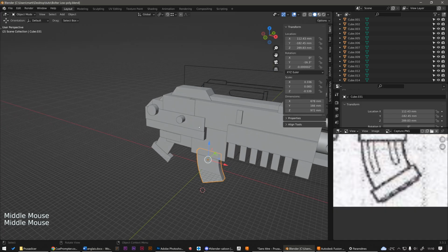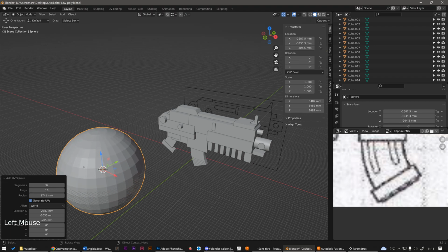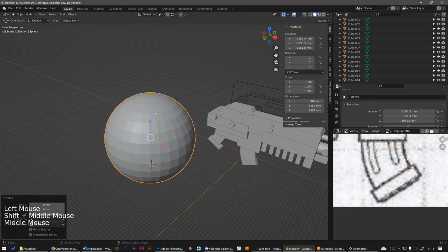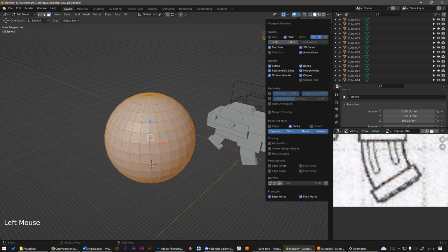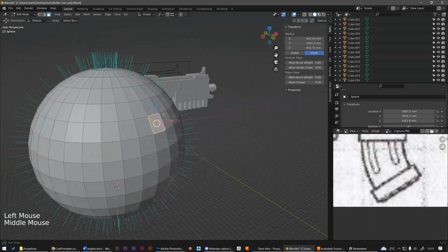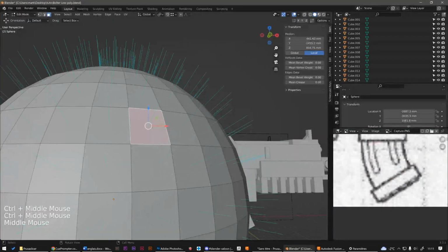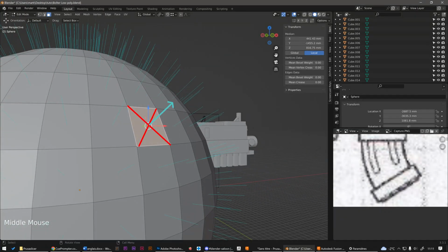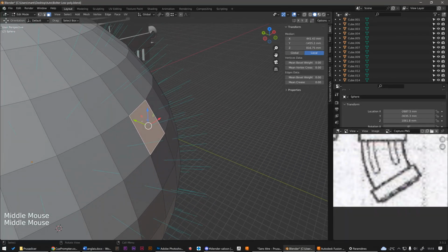When editing a polygonal object, Blender allows us to display each face's normals. To show you, let's create a sphere. Then switch to Edit mode with the Tab key, and in the Overlay menu, I can tell Blender to show me the face normals, and I can increase their size here. And now blue hairs appear on the model, but it's not hairs, it's the normals of each face of the sphere. And if we look closely, each normal's origin is placed at the center of its face and is oriented perpendicular to it.